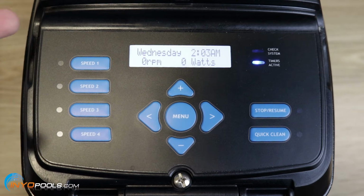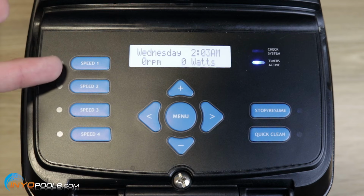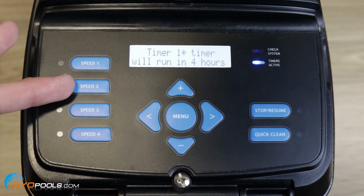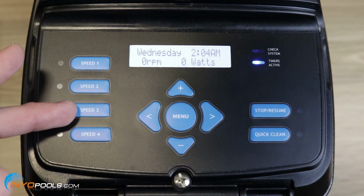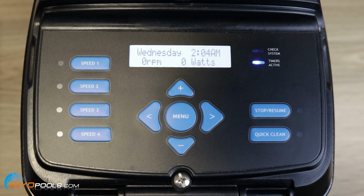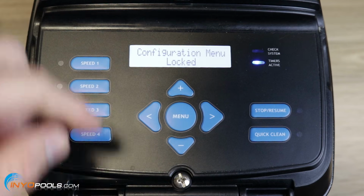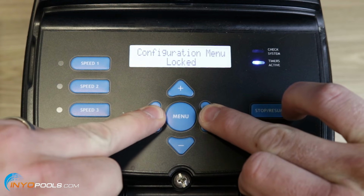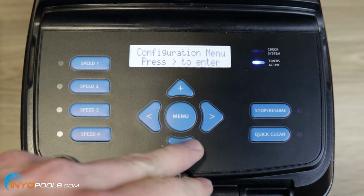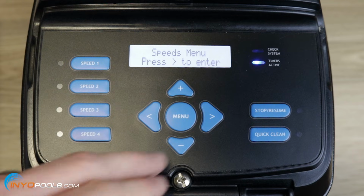Okay, the last thing that you may want to program are the speeds you see here on the left-hand side. They come preset from the factory. Speed 1 is 1,000 RPMs, speed 2 is 1,750 RPMs, speed 3 is 2,500 RPMs, and speed 4 is 3,250 RPMs. So if you want to change those speeds, this is how you do it. You press menu again. If it's locked, you just press these two. All right. And then you hit menu again until you see where it says speeds menu.